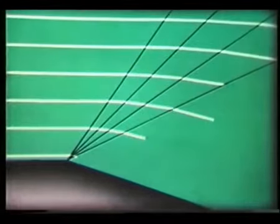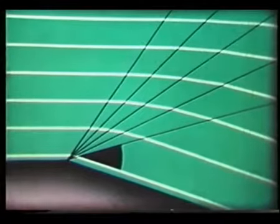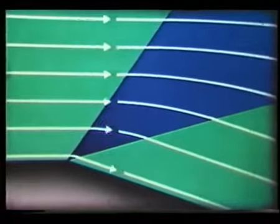An expansion at a corner can be looked on as a series of tiny changes in direction, pressure, and speed. The expansion ends at the Mach angle corresponding to the final speed and direction of the flow. So it is confined to a fan-shaped region between the first and last Mach lines.